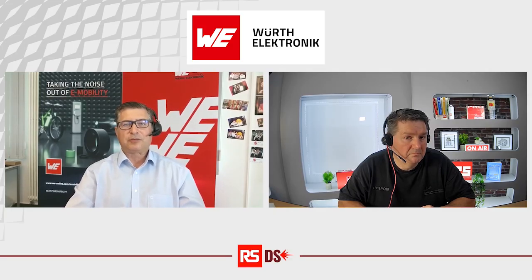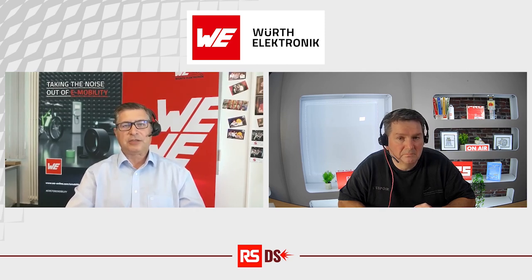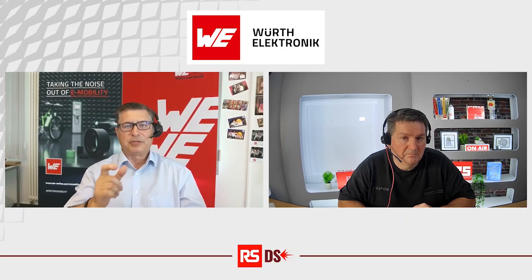I was almost frustrated. What's wrong in this device? Finally, I started to change the ceramic capacitors, and voila, by the second capacitor, I had the lucky punch: I found a ceramic capacitor which was not working anymore, so it was no longer coupling the pulse from the PWM to the MOSFET.